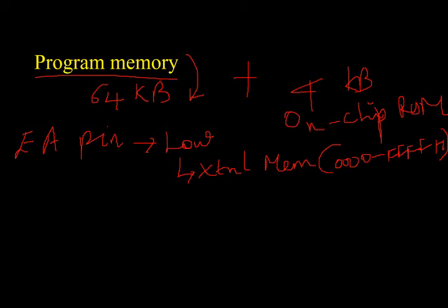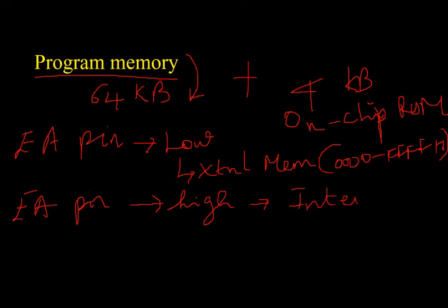If the EA pin is found to be high, it will be accessing the internal ROM. So this is how program memory is accessed.